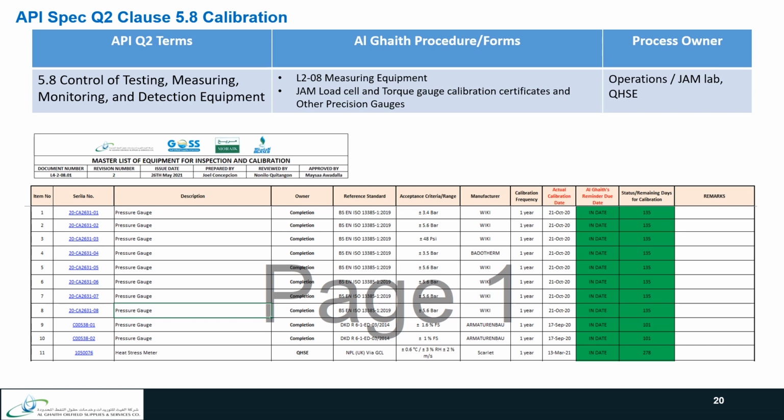All tools need to be kept in a safe storage area to prevent any damage that may affect their integrity. If any of the precision measuring instruments are damaged or due for calibration, they shall be red tagged and removed from service until appropriate correction and recalibration is completed. Herewith is an example of a calibration register where calibration status is tracked for all precision measuring instruments.